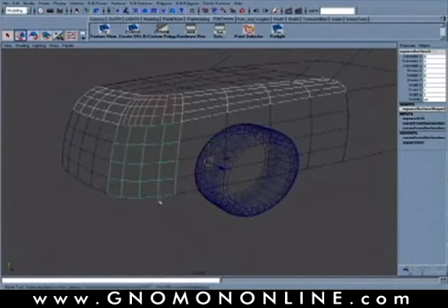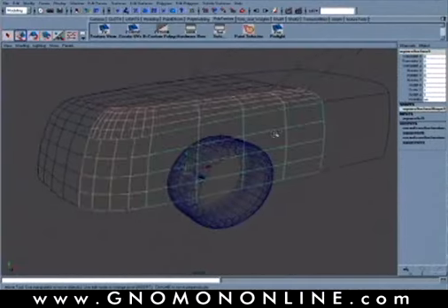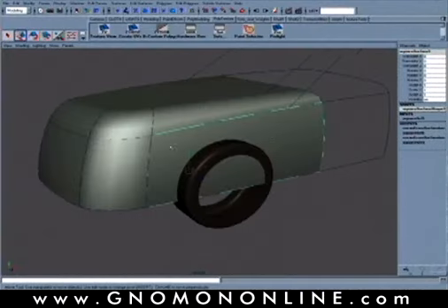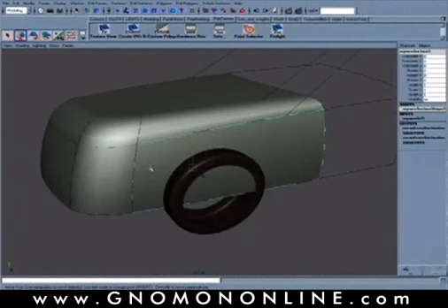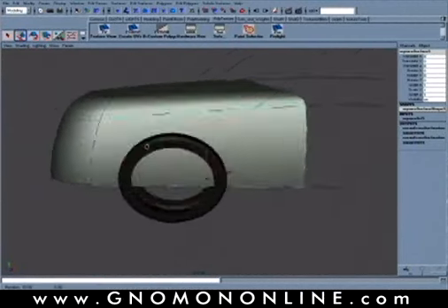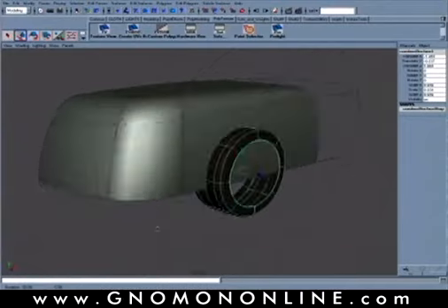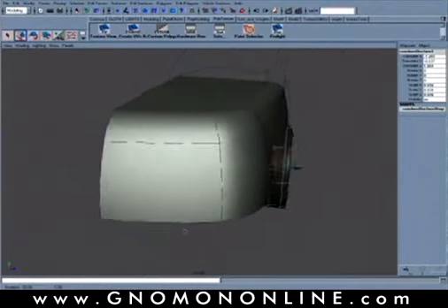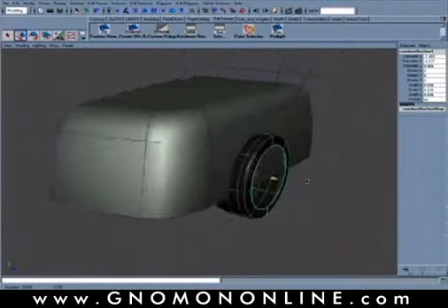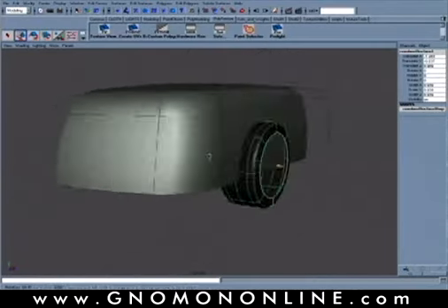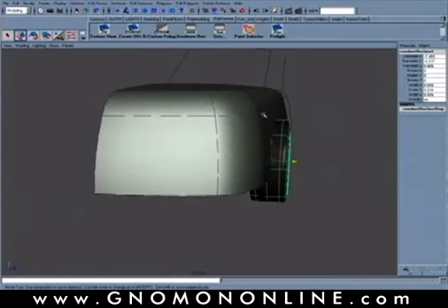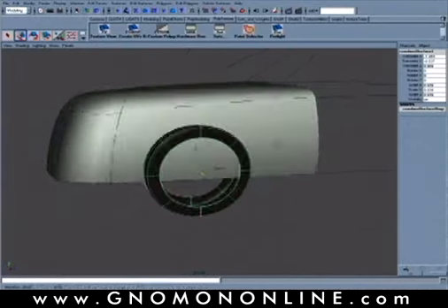But the main focus here is this one quarter panel that we created with a square surface, and I want to taper off of that a new surface that's going to represent the fender for this particular wheel. Okay, so I have a wheel here just as a proxy, a simple revolve form. I'm going to use this as kind of the guiding part of where I'm trying to integrate this new surface out to, basically hitting on that wheel rim section coming out off of here.